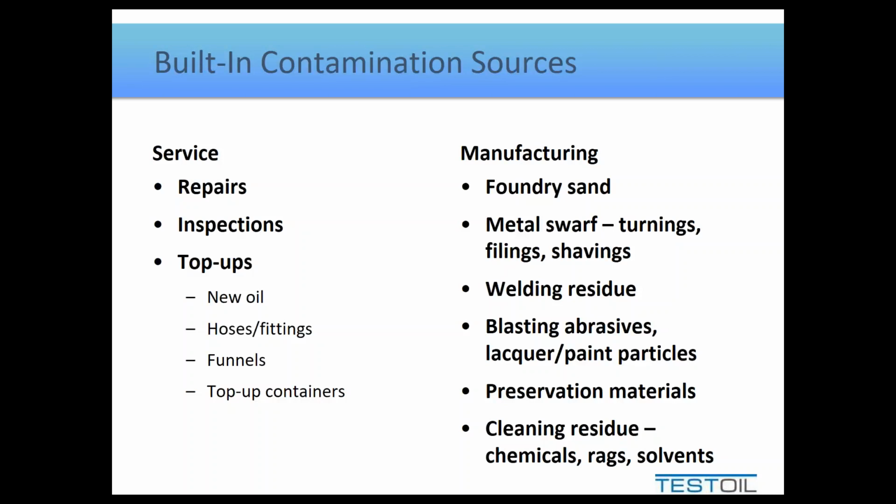Carrying down our list, anytime you apply new piping to a system, if it's being cut or threaded or whatnot, you're going to create a lot of metal shavings. Those metal shavings can be quite damaging in the system. And again, I'm not referring to the ones you can see. I'm referring to all the little tiny bits that are also created that you tend to ignore because you can't see them or don't see them as easily.